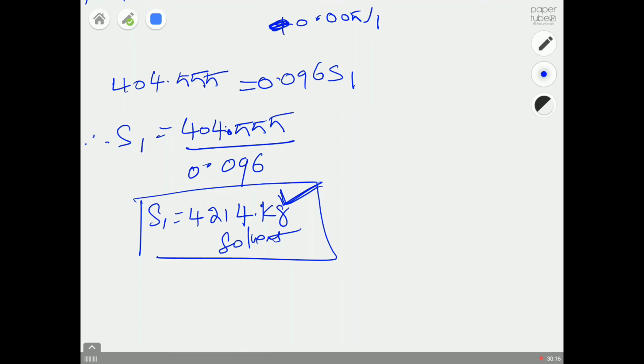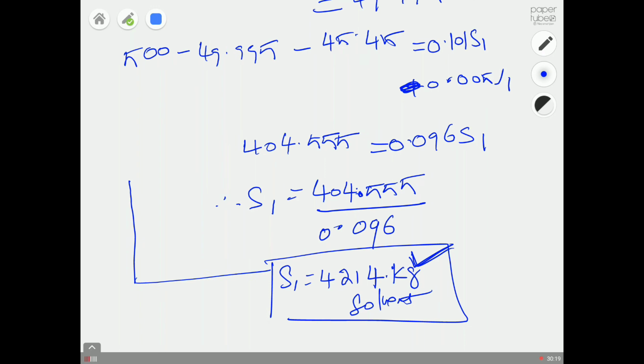So this shows the limitations of liquid extraction. This is our xc versus yc. When we are coming closer to this area, if you need to remove more and more solute from the feed solution, then the requirement for the solvent is going to be higher and higher.